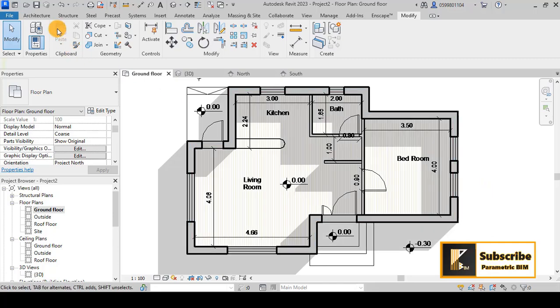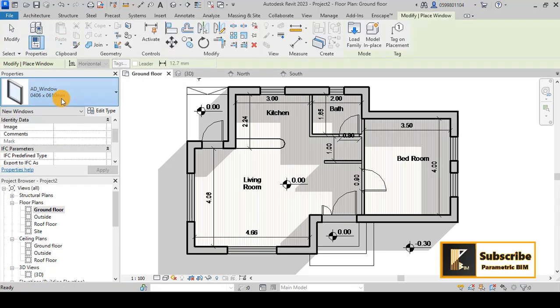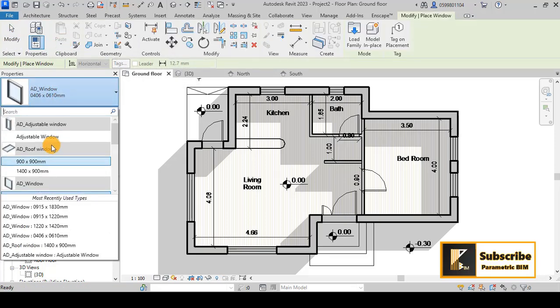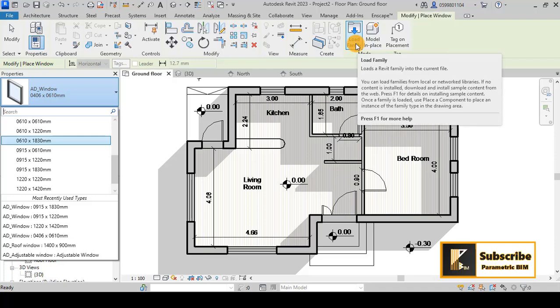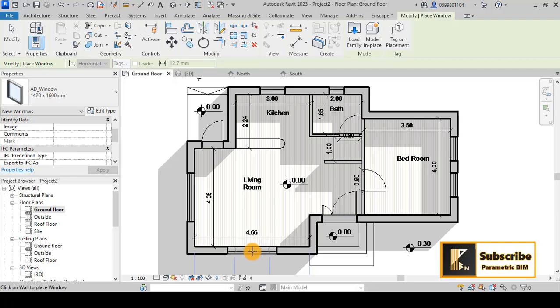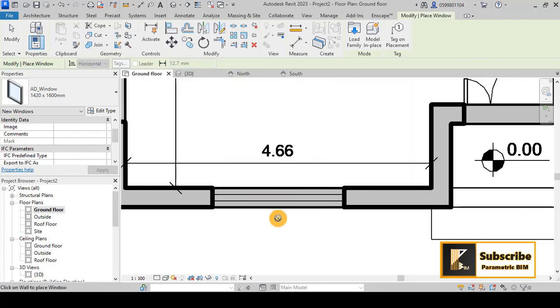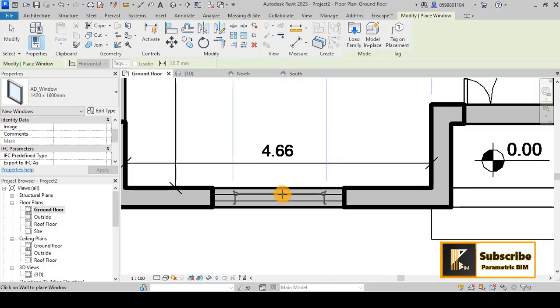So simply you can go to architecture and then you go to windows. You will have some families about windows that you can choose and use in your project. But if you are not interested, you can go and load family from the libraries of Revit. But I will choose now any one and modify it after that for this tutorial. So once I choose, as you see, the window is hosted in a wall.